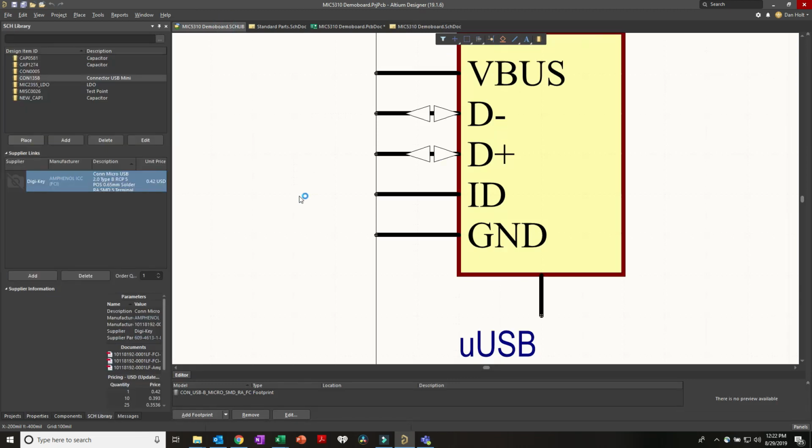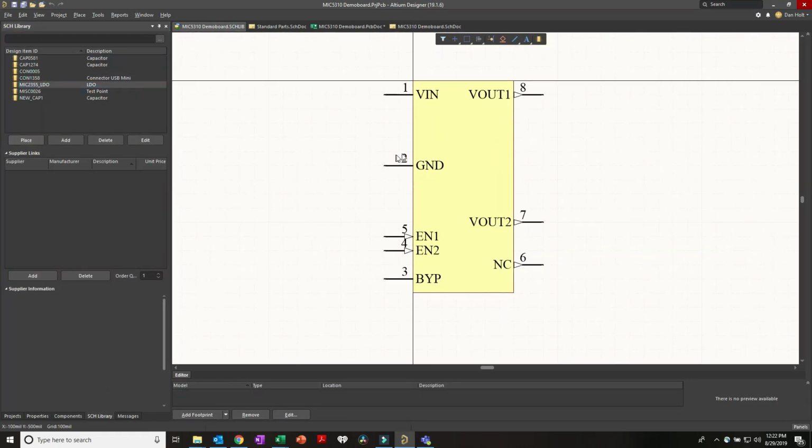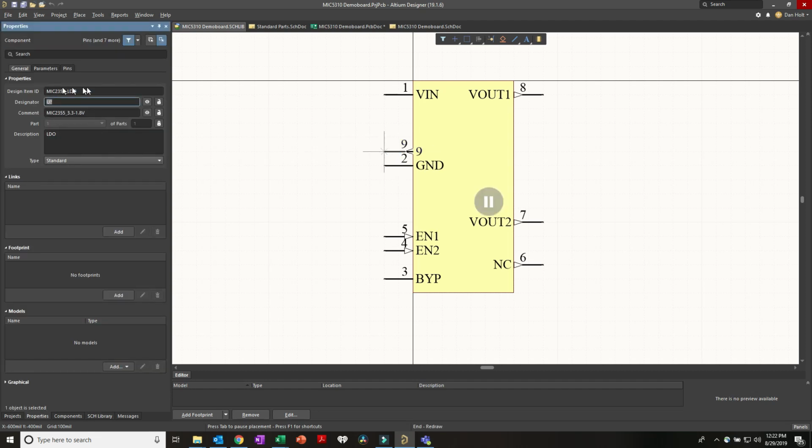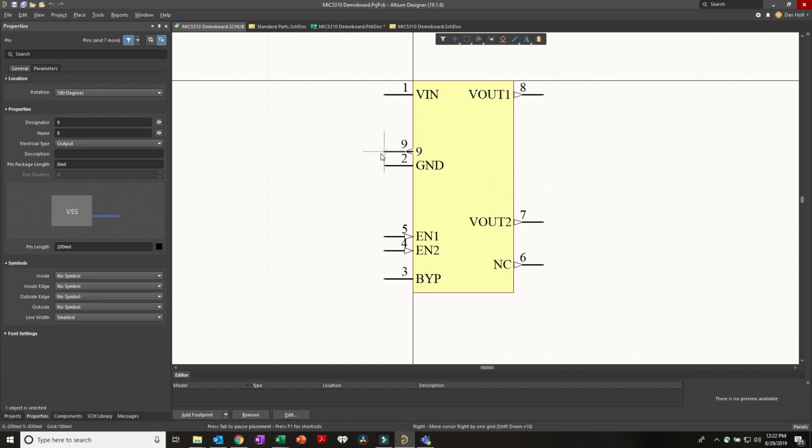Now, let's connect these, and do these with pretty small traces. Tab, 8 mil. Oh, see, this exposed pad right here is not connected to a net. Let's go back to our schematic. Okay, so when we built this part, we did not give an exposed pad connection.